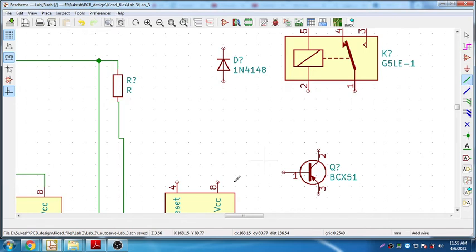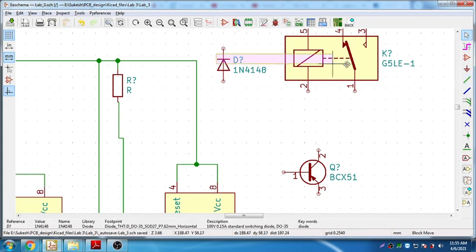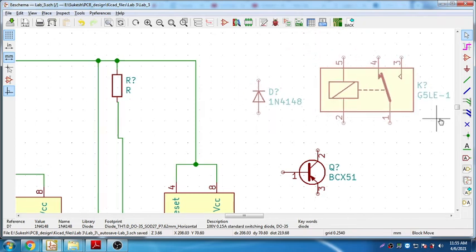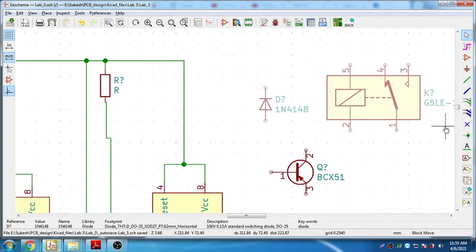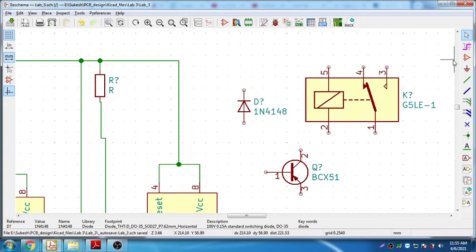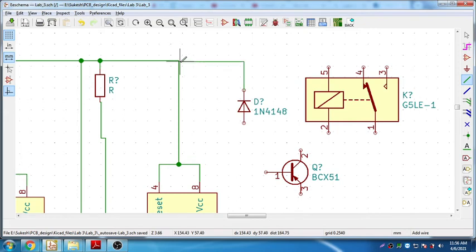Okay, again the pin number 4 and 8 here. Pin number 4 and 8 should be shorted, and should be connected again to VCC here, and this resistor and this will bring down both of these components somewhere here. Fine. And we will connect this diode also to the VCC here.